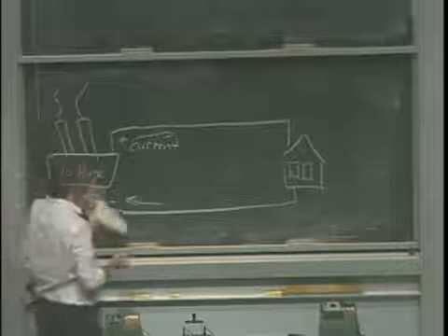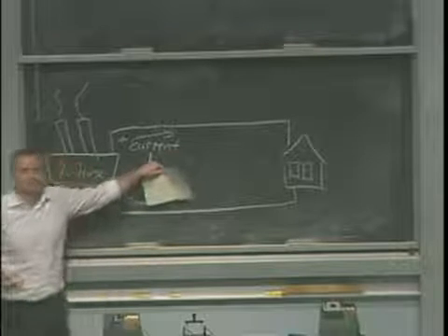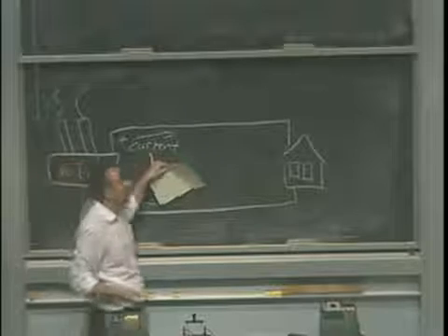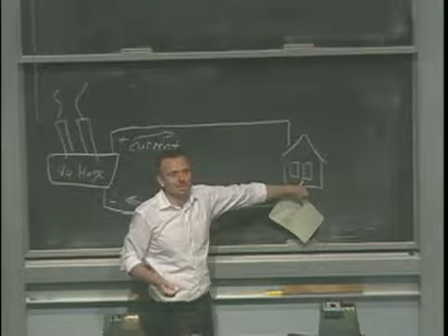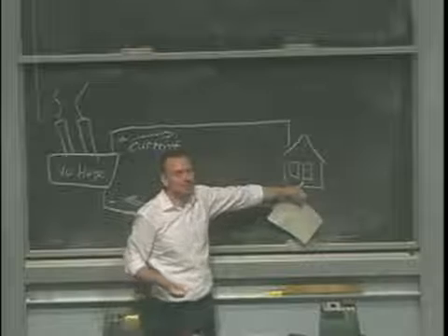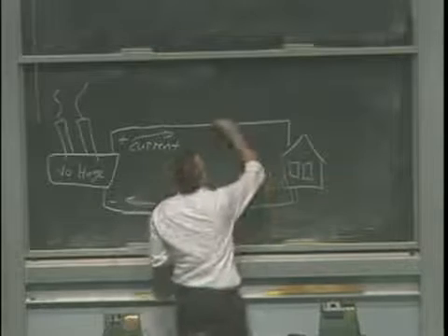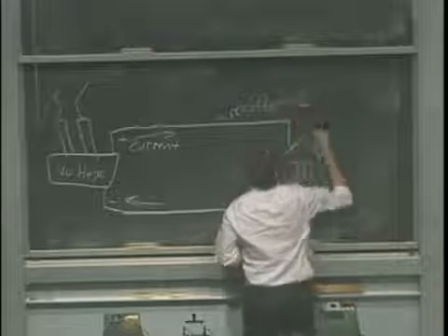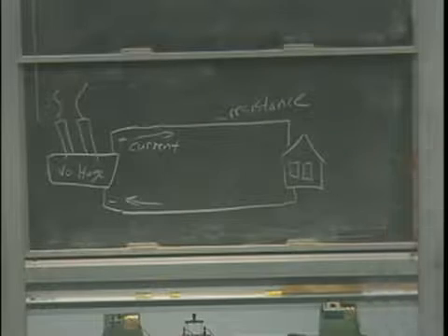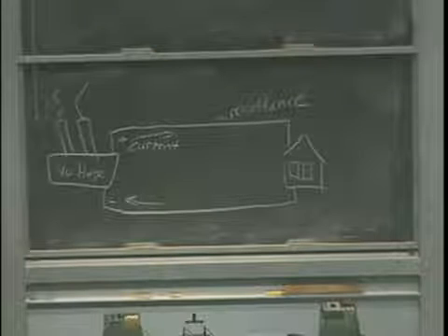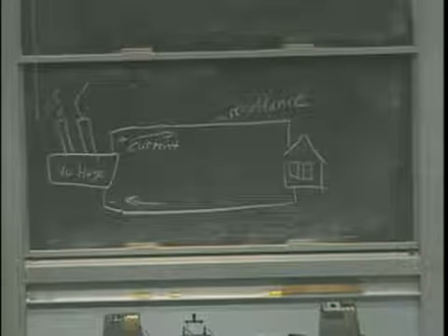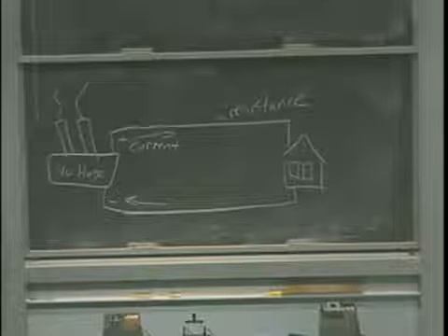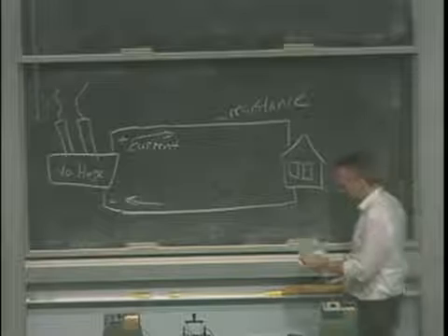Okay, and the voltage times the current will tell us how much power is being delivered from that power plant. And that's hopefully being delivered primarily to the user or to our appliances. But we have to keep in mind that there is a resistance in these transmission cables, and that resistance is going to be dissipating power. The power that we would prefer to be delivered to the cities and homes is instead dissipated as heat along those transmission lines.